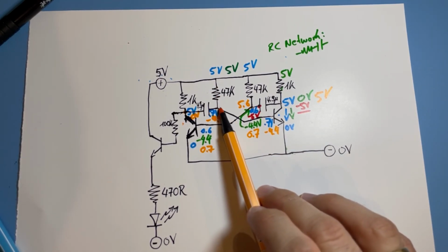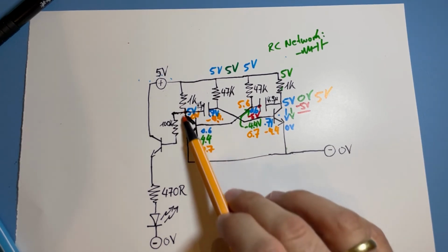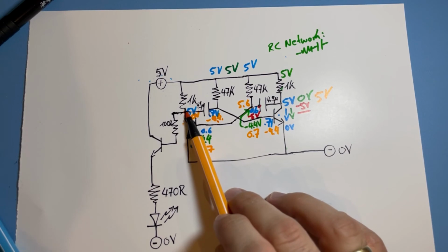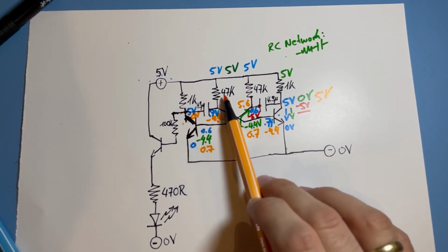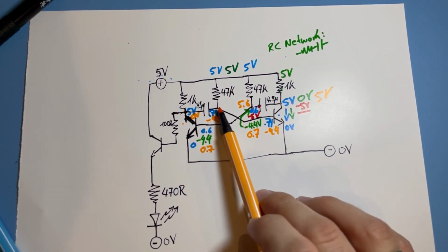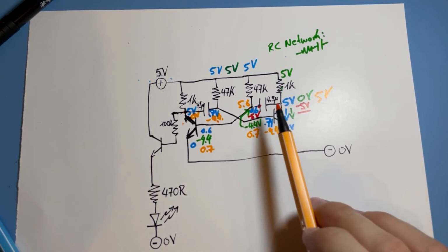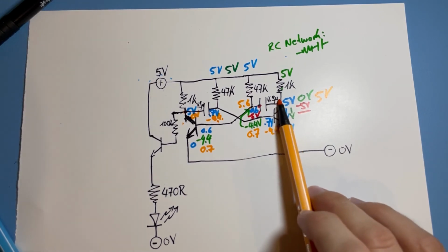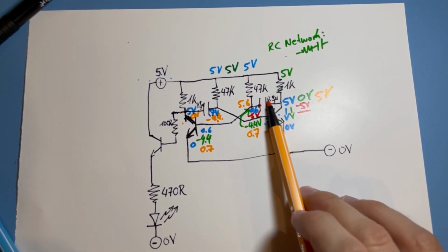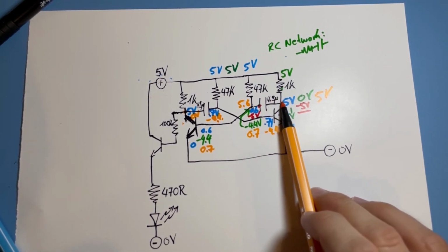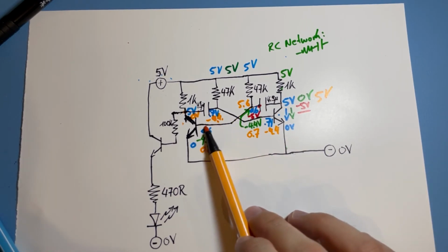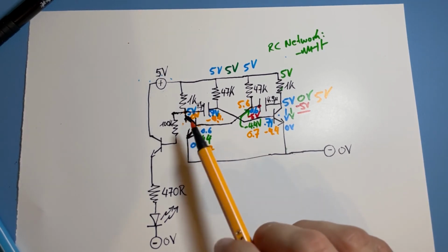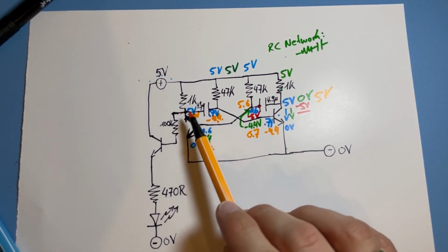And now this transistor is conducting, and there's 0 volt here. And then once you charged up this one to 0.7 volt again, then this one will be conducting again, pulling low here, and then this transistor will be cut off.